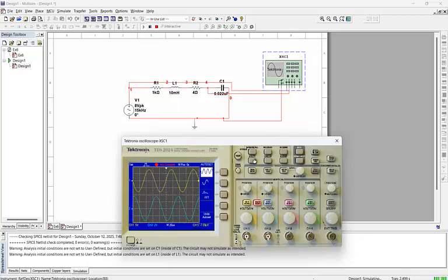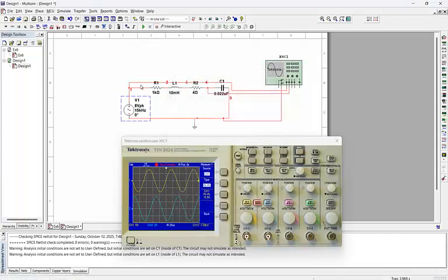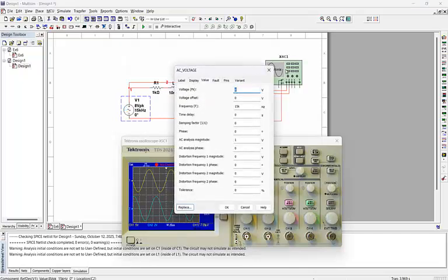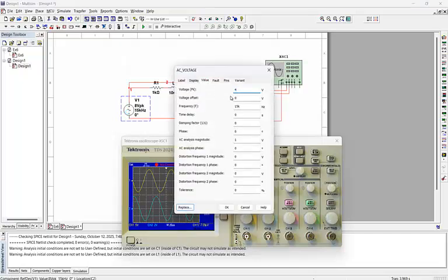And right now I am going to press the measure button. For channel 1 I am going to measure V peak to peak. Sorry guys, this should be 4. I'm going to stop the simulation. I noticed a problem here: for the value of V peak, I used 8, but it should be 4 as peak, since peak to peak is 8.